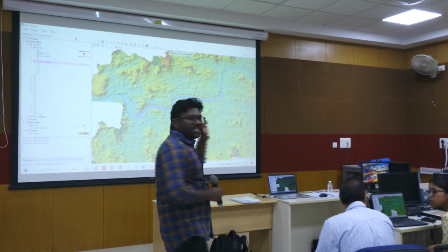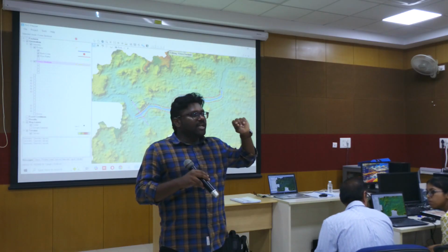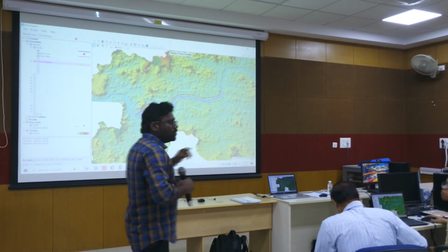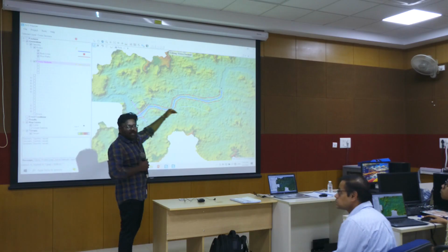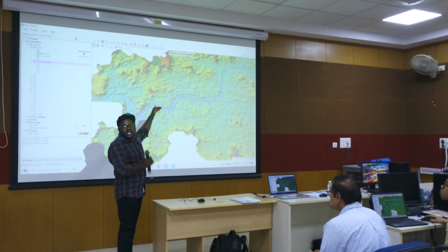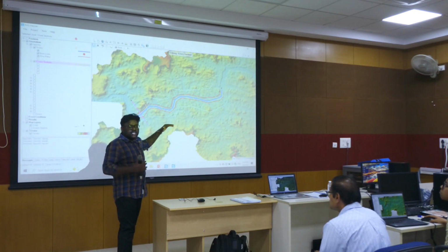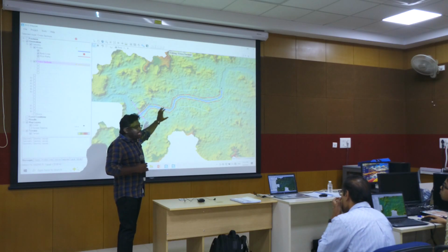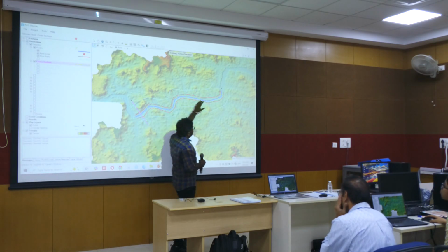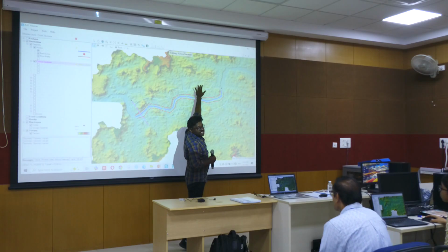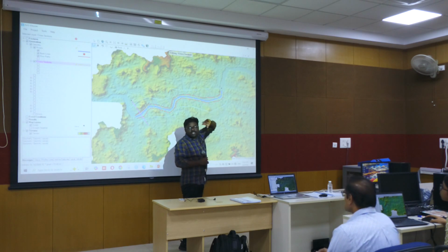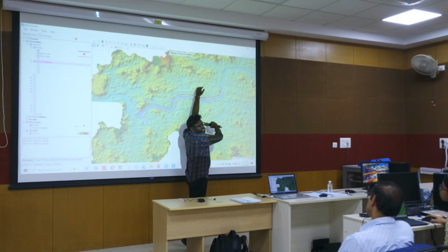While drawing these cross sections, these cross sections will give you river shape, length and width. So when you give the data, water cannot move beyond these lines. When you are drawing the cross sections, give them in such a way that you give the maximum distance. For example, if in a real case water is going beyond this line, in the analysis you won't get that. You will see after the results. Water will be limited within these cross sections only.